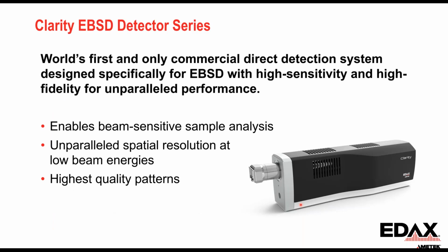So just to introduce the technology in our product, we've introduced what we call the Clarity EBSD Detector Series. And this is the first detector that's commercially offered that's been designed specifically for EBSD. It's a high sensitivity and high fidelity detector, so you can look at beam sensitive materials, you can get improved spatial resolution, you can get really high quality patterns. So it brings a new range of capability that we haven't been able to reach with traditional phosphor-based detectors for EBSD analysis.